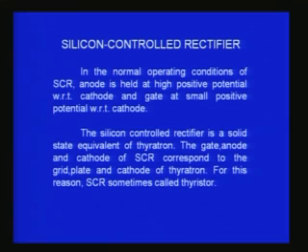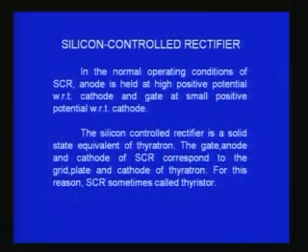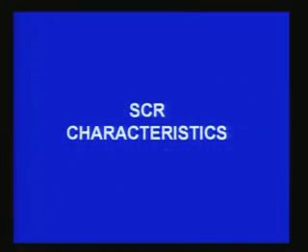Right, now let us assume I do not give any voltage to the gate, then what happens? If I keep on increasing the DC voltage connected between the anode and cathode, you would find at some critical point, which is similar to the Zener breakdown voltage, the thyristor will start conducting due to the forward breakover voltage. Just as in the Zener diode in reverse bias, when you exceed a maximum limiting voltage, you find it starts conducting continuously due to avalanche effect. In the same way this also will start conducting beyond some voltage, that we call the forward breakover voltage. Let us see the characteristics.